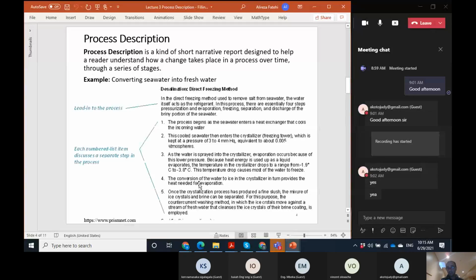It's a kind of text that explains, first, briefly, at the beginning, generally one paragraph. It depends on the process. If it is a small process, just a paragraph. If it is a whole process, a large scale process, maybe a few pages, 1 page, 2 pages, briefly explain the operation, what we expect from this system, what this system is, and then one by one, itemized, state the detail on each step of the process or the steps of the sequence control.